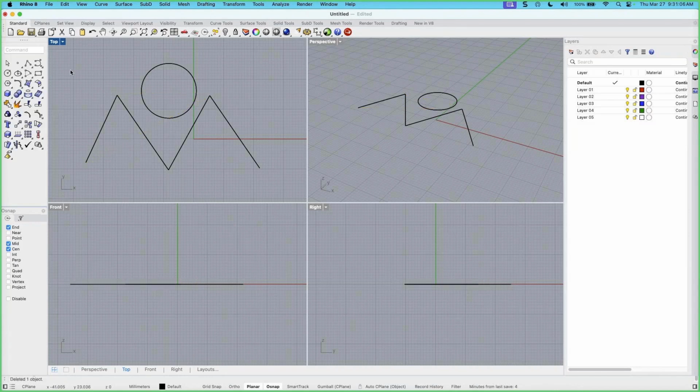Okay, so O-snaps are available unless you hold down the Alt key. It will temporarily disable them. So I'm trying to draw a circle. It'll snap to the end point or the midpoint. If I hold down the Alt key, it will temporarily disable them. There's also filters. We'll probably have the opportunity to talk about them when we do area.